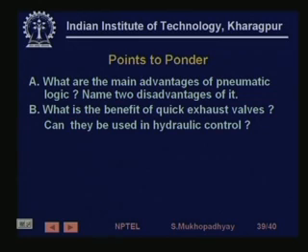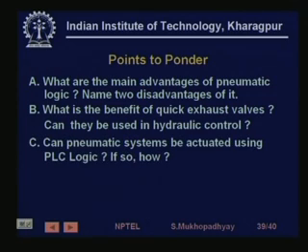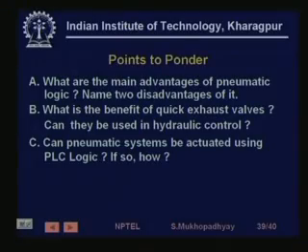What is the benefit of quick exhaust valves? And can they be used in hydraulic control? Of course they cannot be. Can pneumatic systems be actuated using PLC logic? If so, how? Actually, they are in many cases actuated using electric logic. We have seen how a microprocessor can actually control a pneumatic system. So, PLC is actually nothing but a microprocessor, as we know. So, it can surely be used to control, but if you have an air pilot, we might need an I2P converter. That's all.